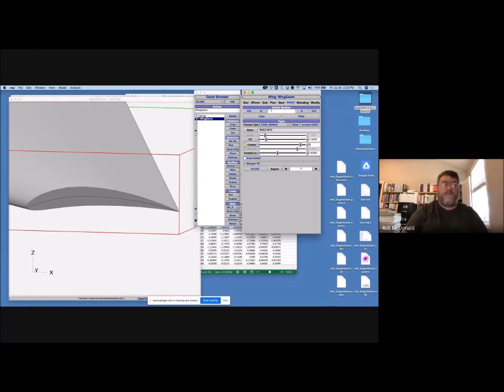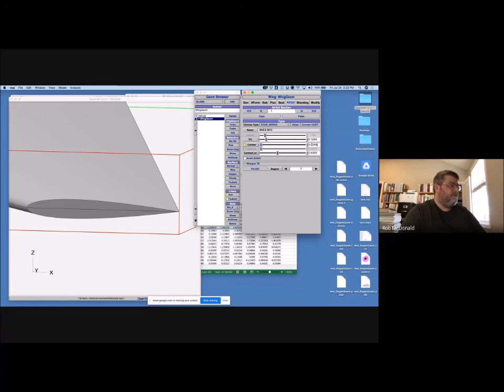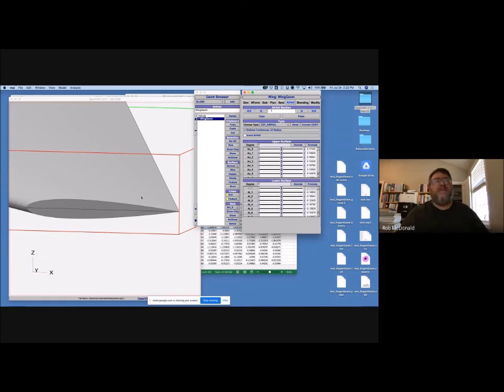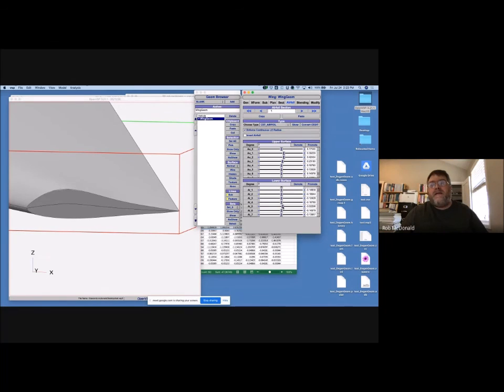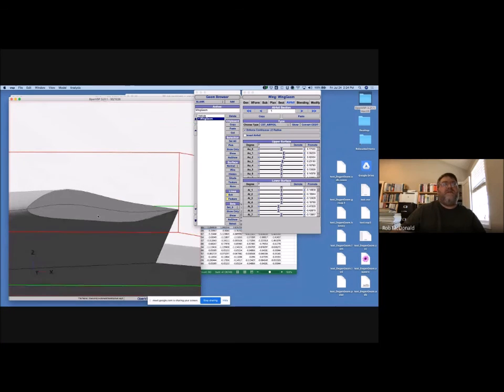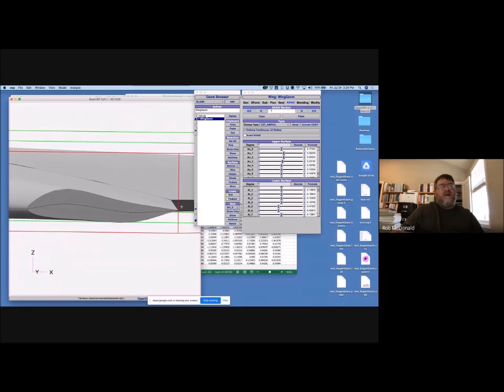Whereas if there's zero camber, the airfoil itself is neutrally stable. Okay, and so what you can actually do, this is going to get a little complicated, but if I come in here and I adjust my airfoil up a little in the front, but then down in the back, I can have, and this is very crude, a camber line that goes up and then down, and then it comes back up to the trailing edge. And you'd really probably want it more like that, right?